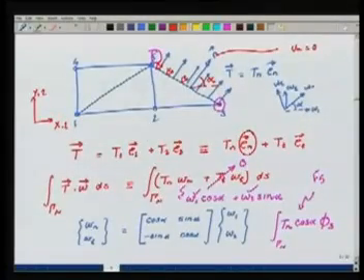So we do everything that we do in the standard way, assemble the global stiffness matrix and the load vector, and then go and impose this condition to eliminate one of the unknown coefficients. That is, I can write here on this edge the un as equal to what?